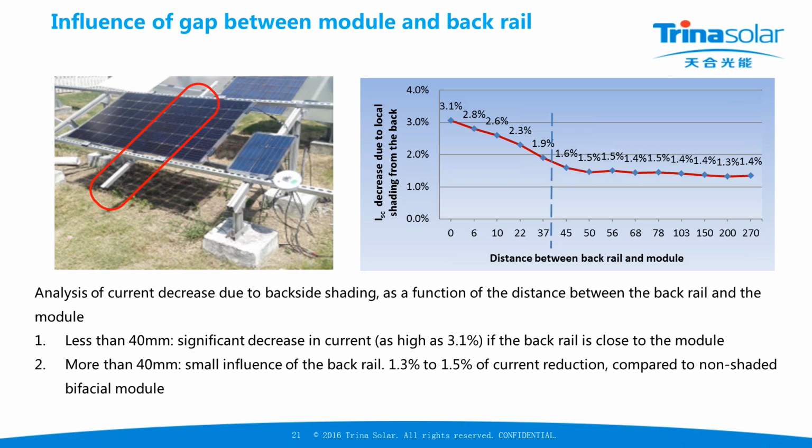Effectively, if you have grass, for example, which is a relatively good reflector, between 10 to 20%, when the grass dies and shows a dark ground, the albedo drops. And so you need to maintain a very highly reflective soil underneath the modules. The best is to use sands. Reflective sands is probably the best albedo you could get, and with the lowest maintenance. Or if you could paint the background white, if you're on a roof, for example, it's also a good point. But you have to make sure that your albedo doesn't degrade over the years.